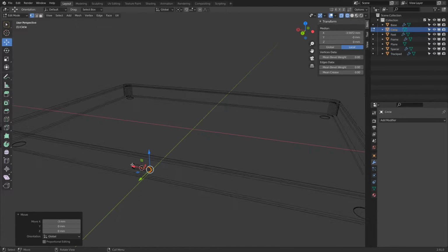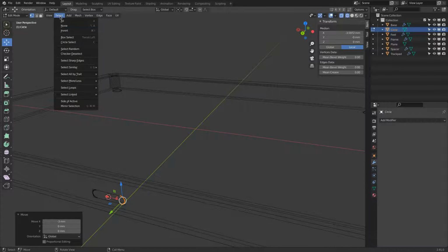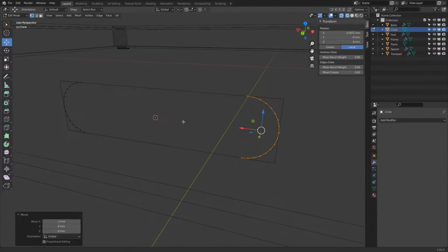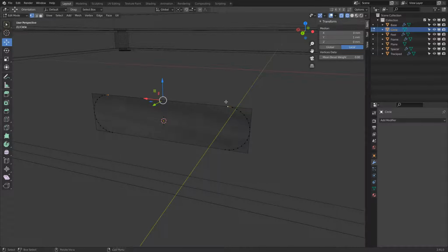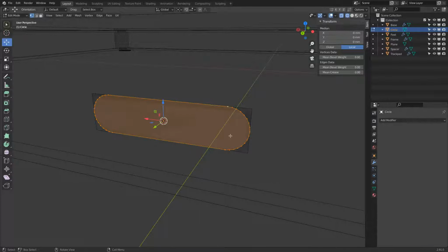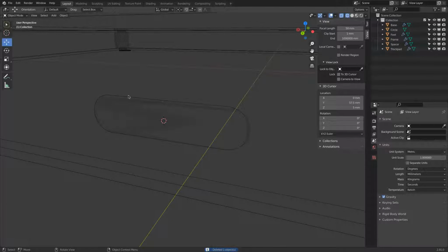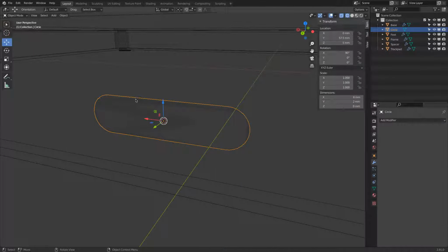Now, with all this done, we can go to a 3D view, view frame selected, then top and top. We select, press F, press A to select everything, press F. There we have the whole piece selected. Very nice. Then we go to object mode. This rectangle we don't need anymore. We can delete it via the delete key or X.